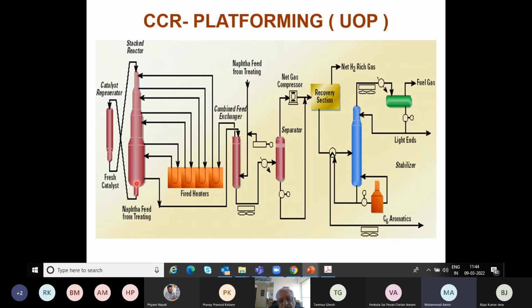And once the gases reach the bottom, you withdraw them and put them through the feed effluent heat exchanger, where it preheats the feed. And then you take off the rest of the heat by a fin fan cooler, or what we call air coolers, and then the rest of it by a water cooler, that is using cooling water. We call this a trim cooler in the industry.